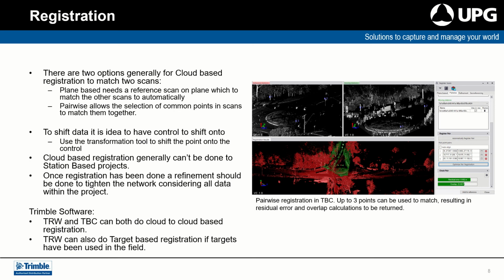Cloud-based registration isn't done on station-based projects. So this is a consideration when using the SX series of instruments. You will not be able to use the cloud-based registration on anything that has been done using a station-based setup. For this, it's because your registration is done against the setups, not necessarily the clouds themselves.